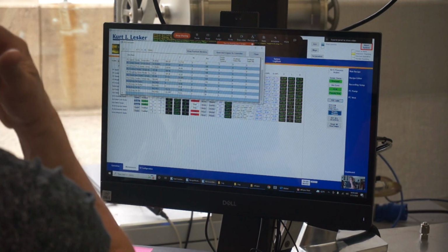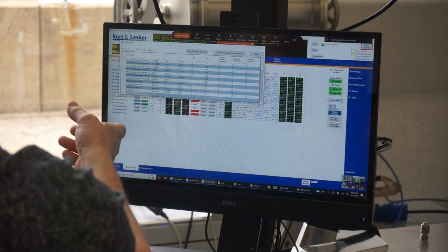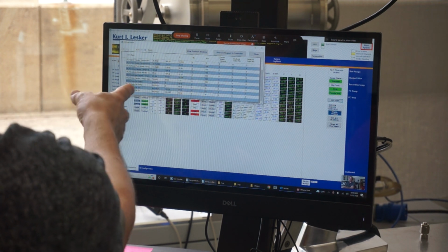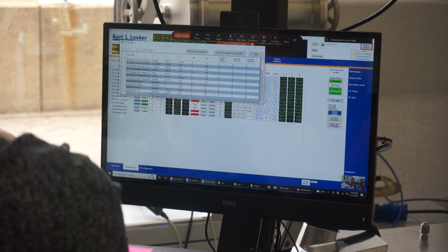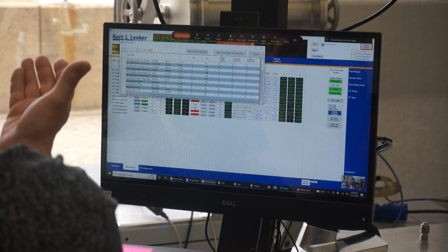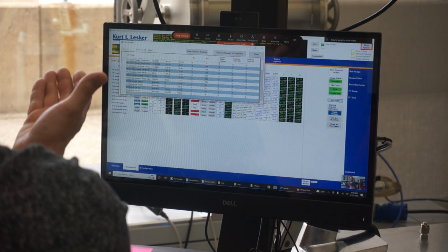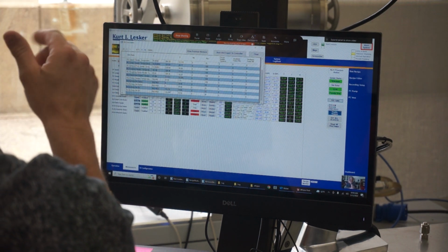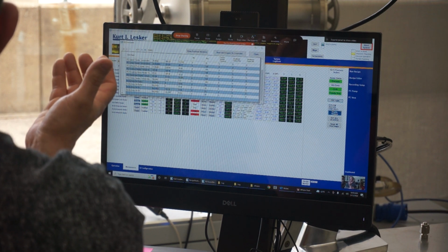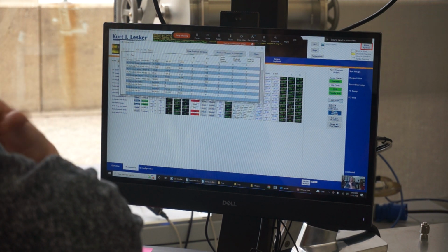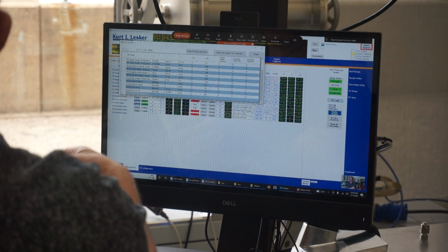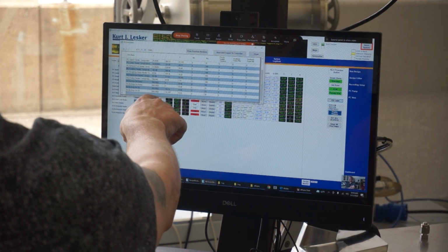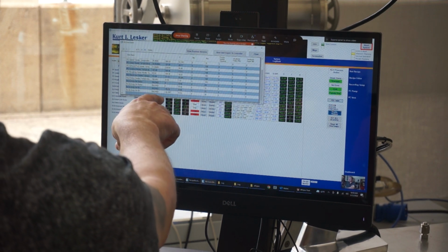I just did this like 2 or 3 weeks ago, running the recipe on zirconium with these PID values, the overshoot from 75 degrees C was 0.65 degrees, and then the undershoot after it was like 0.15 degrees, but still within 1 degree. You're not going to thermally decompose that material. That's how you want that to run. So in regards to the ampule heating, that's the reason why you have 2 different sets of PID values.